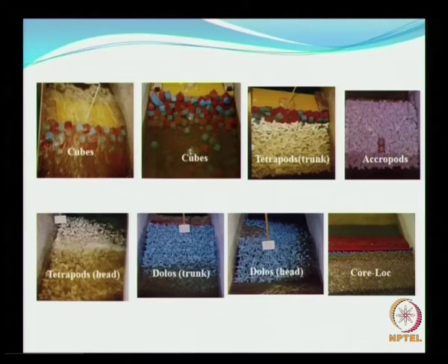So these are some of the tests that have been done in this particular flume pertaining to harbor structures. That is, as I said earlier, we have different sizes and different shapes of stones for breakwaters that are used as armor layers, so cubes, then you have tetrapods, acropods, dolos, and also the core lock, etc., and all these things have been tested in this particular wave flume.